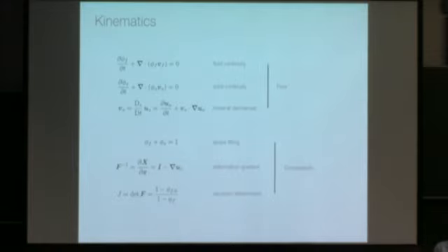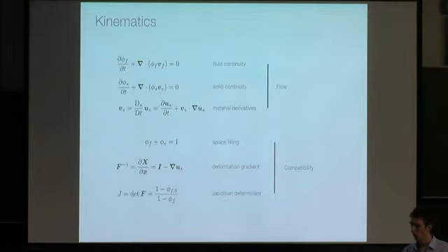That is assuming that rho_s is constant. Yes, yes, incompressible constituents. Yeah, absolutely. How is that different from the divergence of displacement? We'll come back to that. Yeah. So the short answer is that this is the large deformation version of the divergence of the displacement field. So for small strains, it is the divergence of the displacement field. But there are nonlinearities here that are not there.